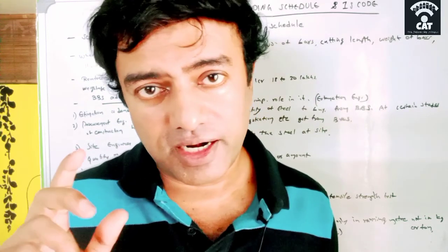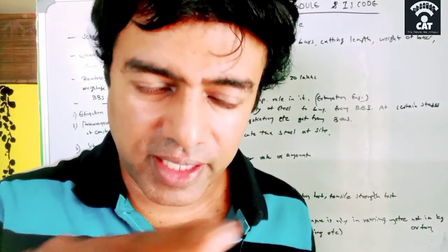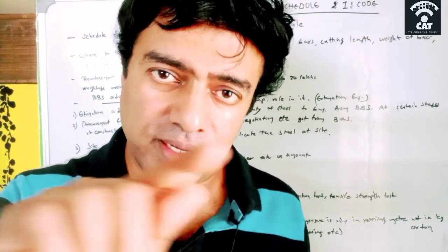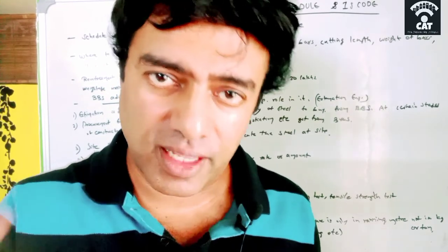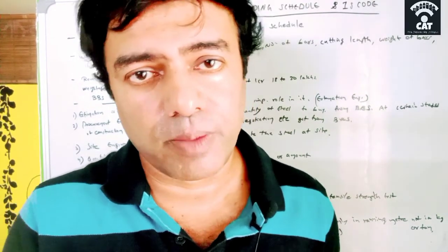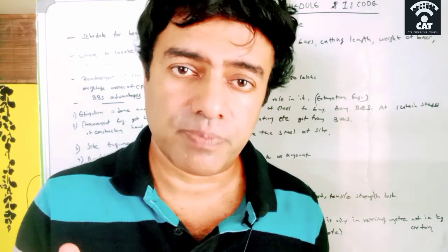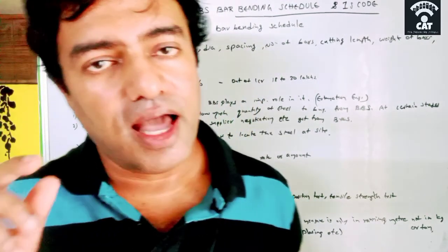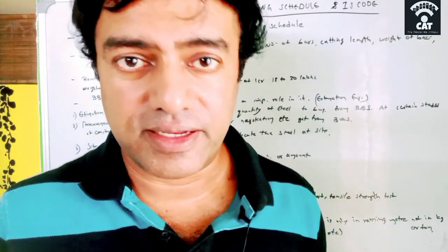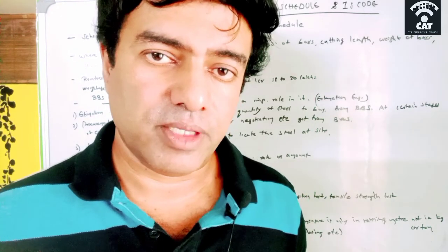He has to find out the cutting length and also the bending length, how much bending should be there, at what angle, and how much length it should be. Everything he needs to prepare from the BBS. So BBS plays a big role at site for the site engineer. He also gets an advantage from the BBS.